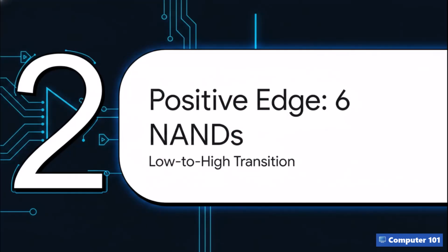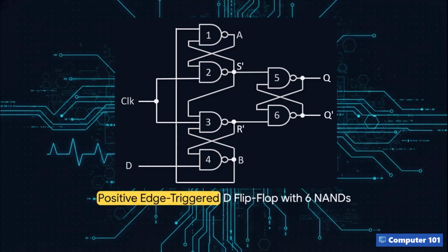Section 2. Positive edge with 6 NANDs. So how do we actually build this digital shutter using logic gates? Check out the sheer elegance of this positive edge-triggered design. We're looking at a 6 NAND gate configuration here. Over on the left, you've got your two inputs, the clock and the data input, D. Notice how they map directly into this cluster of 4 interconnected NAND gates.